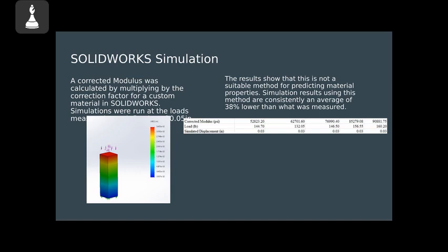The results for this were a little unexpected because they were very consistently at about 0.03 inches of deflection. They hovered a little bit around there. In the table on the right, you can see it ended up rounding a little bit. But it was relatively consistently around 0.03 inches, which is really interesting because that is not what the deflection should be, because each load measurement that we inputted into SolidWorks was recorded at a deflection of 0.05 inches. So something is wrong with our methodology here.